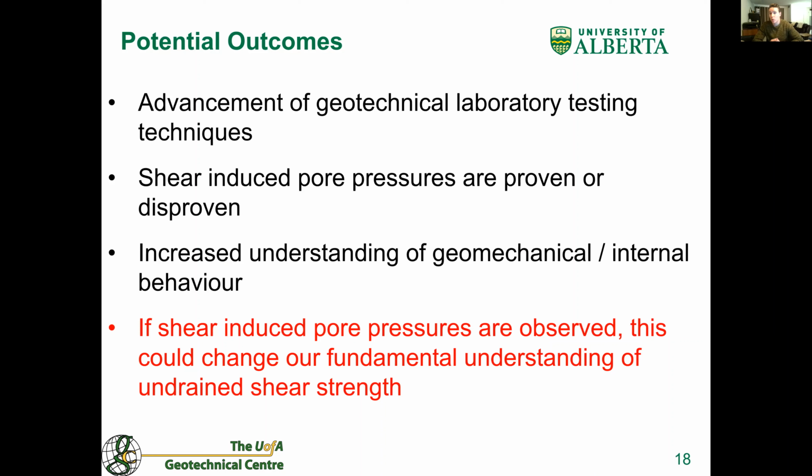Traditional triaxial tests that implement stress-controlled boundary conditions are applicable to many geotechnical applications, however, may fail to capture all the variables of larger problems such as tunneling projects, nuclear waste repositories, tailing structures, and large landslides, just to name a few. The preliminary evaluation of field data from Mont Terri appears to show something that resembles shear-induced pore pressures. One of our major outcomes from this program will be to either prove or disprove the existence of shear-induced pore pressures as a whole. Regardless of this outcome, however, the work we do will help to advance the current geomechanical understanding of over-consolidated clays and shales, with a specific focus on pre-peak strength internal pore pressure behavior.